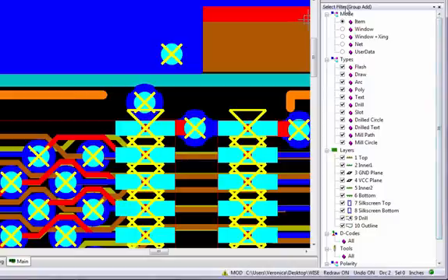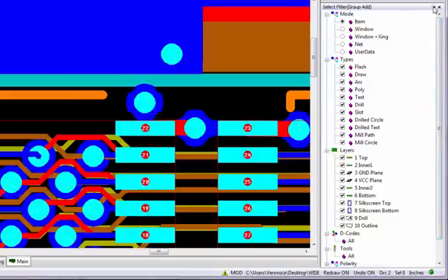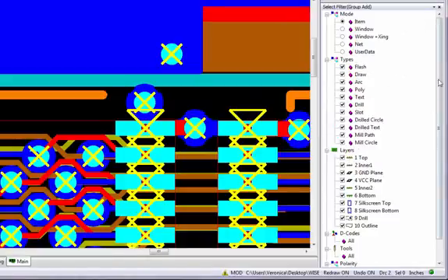Again, just like with the Navigator, Item Properties display, and Color bar windows, the selection filter can be moved, resized, its height expanded to fill the available space, and closed at any time. It will automatically appear again when a function requires it, or you can use the View Toolbars command to unhide it. In the Select Filter window, you can choose from many options to control the data you want to process. Mode options include Item, Window, Window Crossing, Net, and User Data. These define how items will be selected, and the available modes depend upon the command function you have chosen.